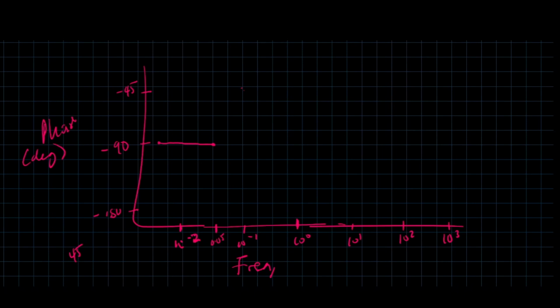So up to this position, this slope is going to be increasing by 45. Next, at that frequency of 1, we see no change, just 0. We see no change till we got to 5, and 5 in this case is at this half position. So at this point it stops. Then at that 5 we see a dip by negative 90. So we're going to dip down by about negative 90.